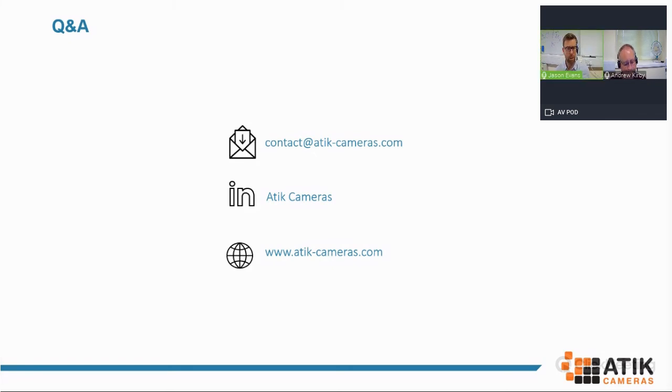What are the key characteristics of an application that would determine whether CCD or CMOS is better? I suppose we've covered that to an extent through the course of the presentation, but from an application perspective, things like speed, light levels, and the optics will play a big role. If you need high frame rates, for example, something which is a bit more live, let's say, then CMOS is more likely to suit your needs.